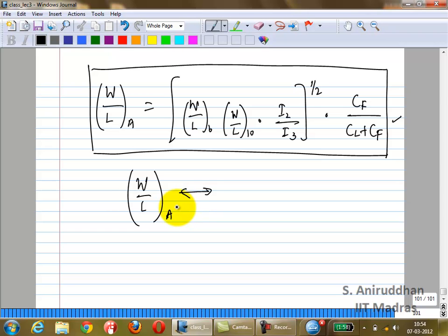What we'll do, okay, Friday we want to have a tutorial, so maybe on Tuesday's class we'll try to look at it the other way, right? So let us say you want to use a resistor. How would you do it? Let us say you want to use a resistor RF. Then what do you need to do? You need to make sure your GM tracks the resistance. Okay? And you need to make sure your final, if you want pole zero cancellation, you need to get a relationship between a ratio of resistors. Right? In other words, RF should be proportional to some resistance.